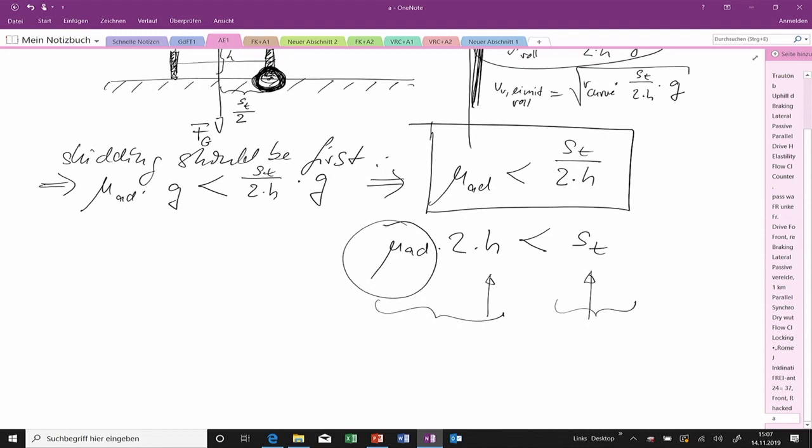And now you know what happens if a system which is able to oscillate is excited with the right frequency. Yeah? So if I not just keep it constant, but I go up and down, and here's the spring and here's the mass, and if I exactly meet this frequency of that system, then it will end up with very, very high oscillations. This is a so-called resonance catastrophe. And this could happen with the car.